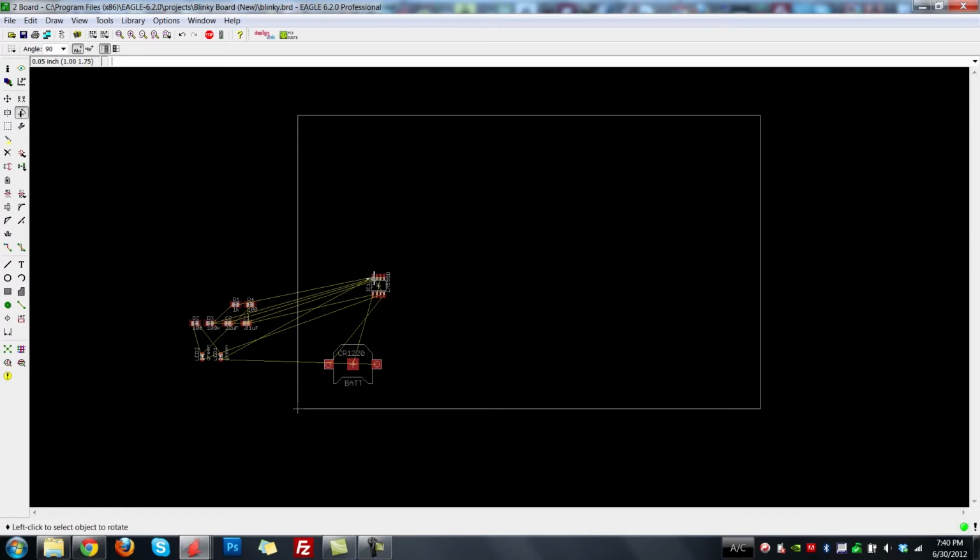And part of this will be up to you, but really you'll want to define it based on what your connections are like. You'll want to place the components so you can draw the shortest connections possible, and ideally so that you have the shortest amount of vias possible.